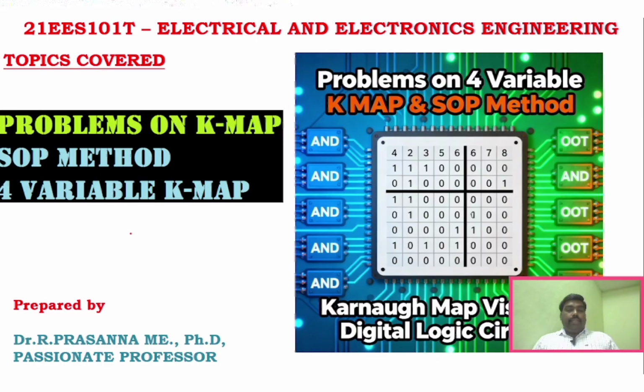First thing you have to understand is which K-Map we have to use, right? We can determine it using two things. One is, if the question is given like this, A, B, C and D, you have 4 variables, right? So it is a 4 variable K-Map. Or else, if the question is given only as Y, you can understand from these numbers.